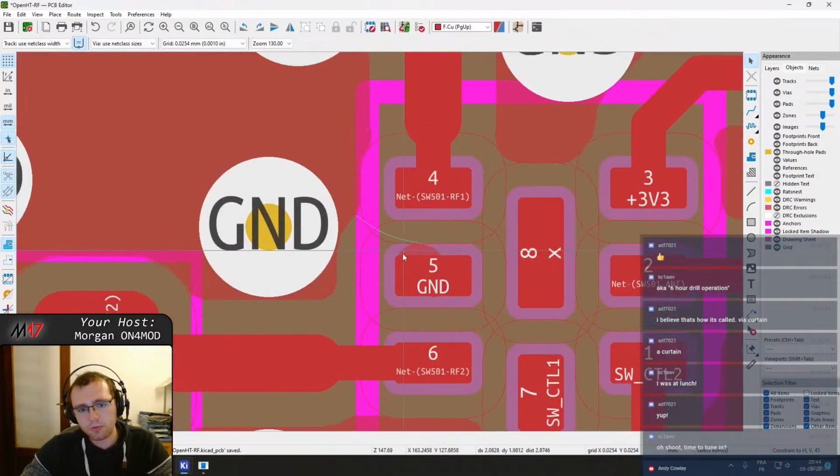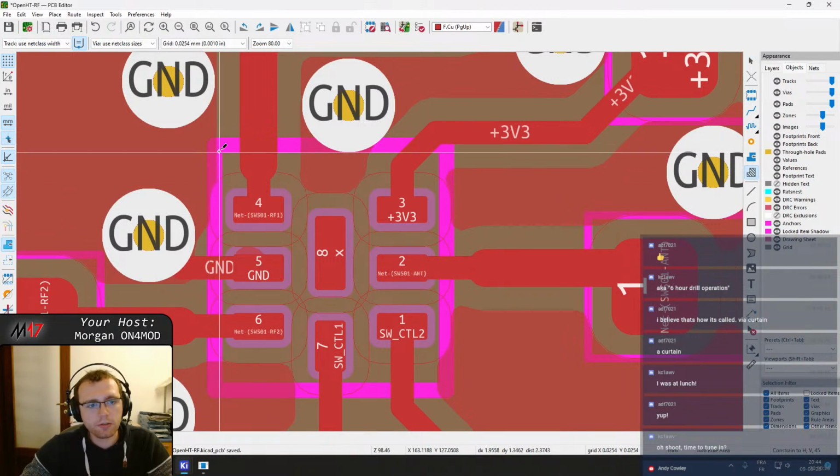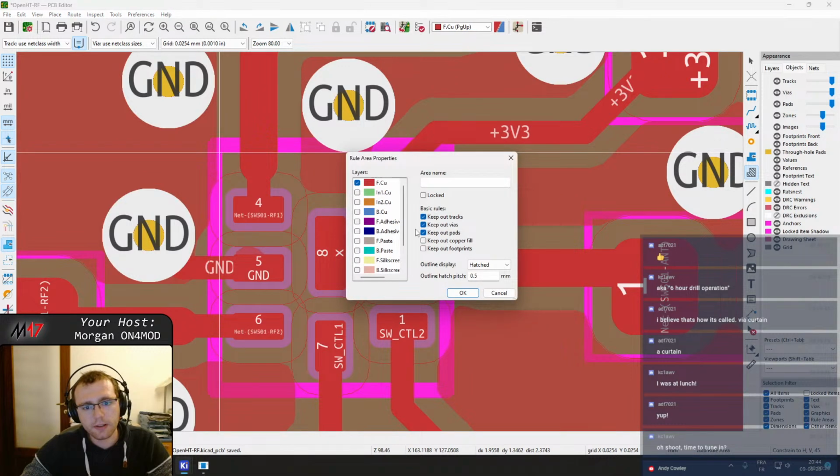Oh, this poor ground pad isn't connected. There you go. Let's put a keep out under this component because I don't want the...